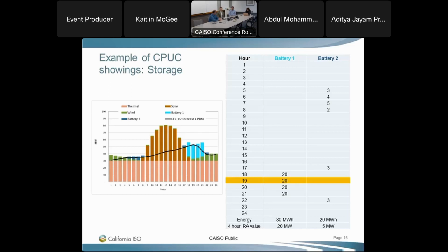Yeah, Noah, this is Catalin. I can probably solve that problem for you. The QC value is established way before the showing. The QC value is the megawatt hour of the resource divided by 4, limited by their Pmax. You can never exceed your Pmax, but it is the megawatt hour the resource is good for divided by 4, limited by the Pmax of that resource. So that's how QC is established. Then the LSE can take that resource and spread it however they want in the PUC 24-hour showings. And then if they use it as RA, they need to make a corresponding showing to the ISO on a totally different template up to the QC value. So if they purchase 100% of that resource, they need to make a 100% showing with the QC value for that resource that's established at the ISO, which is the one we talked about before. It's a single value.